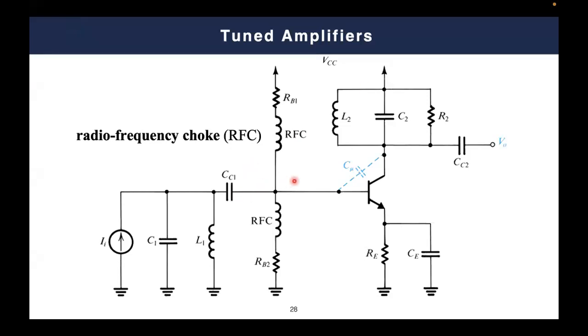Okay, so a very critical problem that occurs in this design is related to what's called the parasitic capacitance. As you know, my dear students, this is what we call a bipolar junction transistor, which here is an NPN transistor. And this means that you have an NP junction here and an NP junction here. From our understanding of the principle of NP junctions, an NP junction in reverse bias has what's called a capacitance effect.